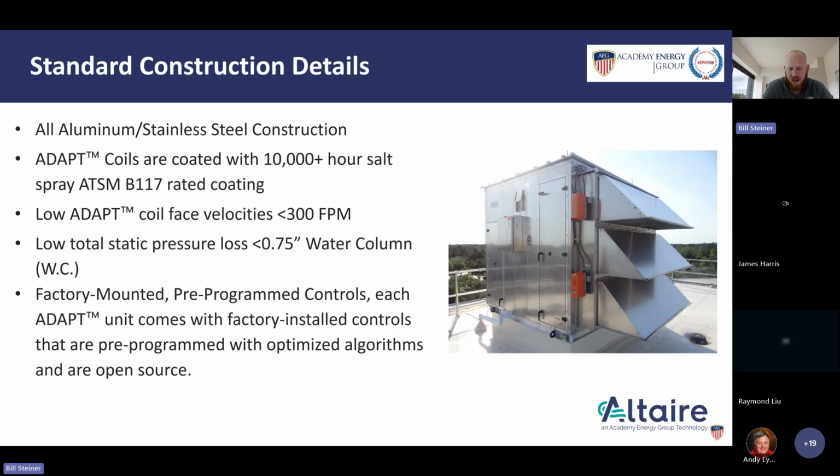It's a really humid day, we've got like a 75-degree dew point or something crazy, we're running at 500 feet per minute, and we're bringing gallons of water out of this thing every minute. You're going to get carryover. And again, the next thing downstream is typically the filters, and those are the last things that we want to get wet. Not that we want moisture anywhere in the unit, but the filters are the worst things to get wet. So again, another good reason why we run this nice and slow.